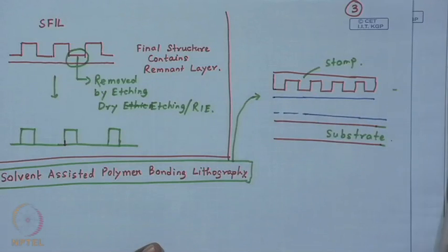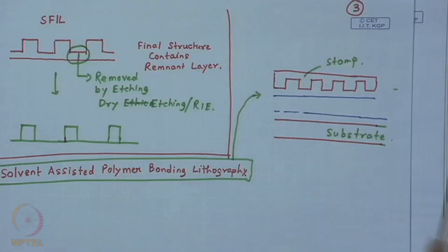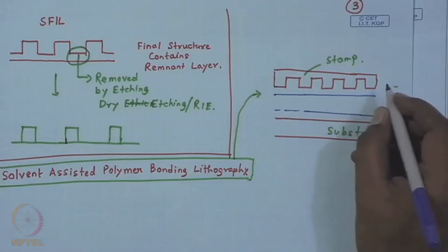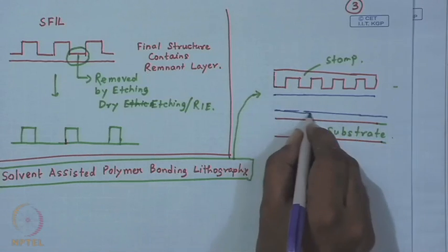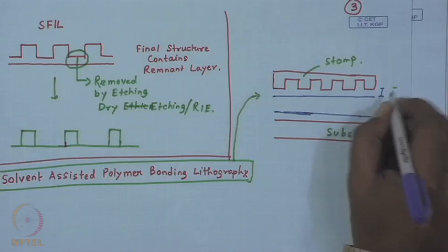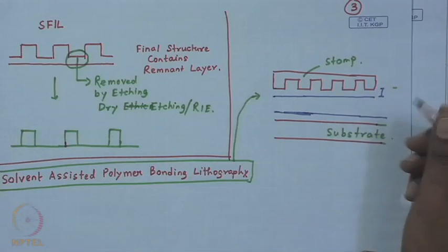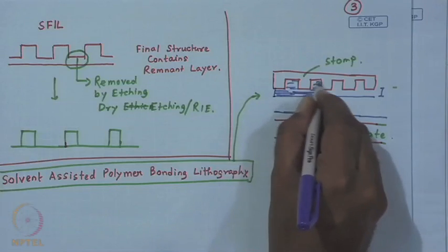And in the previous class we have talked that when you try to coat a topographically patterned substrate with a liquid by spin coating, what happens? So, you might get discontinuous structures, you might get continuous structures with undulating top surface, or you can get a continuous structure with a flat surface. The key being that if the height of your liquid layer is significantly larger than the feature height, then it becomes flat. So, you start off with a layer of polymer,